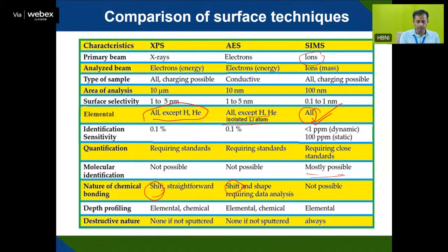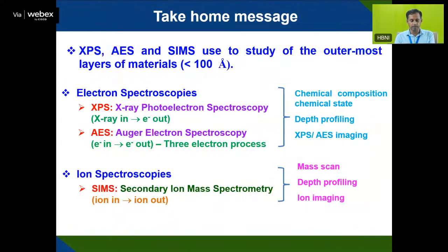So depth profiling, element analysis and chemical analysis are all possible with these techniques, XPS and AES. Regarding destructiveness: if you only spot-analyze, it is non-destructive; otherwise, depth profiling can be done in angle-resolved XPS. In AES, only the spotting case is non-destructive, since an ion beam has to be irradiated on the sample surface, and a primary ion beam is always destructive.